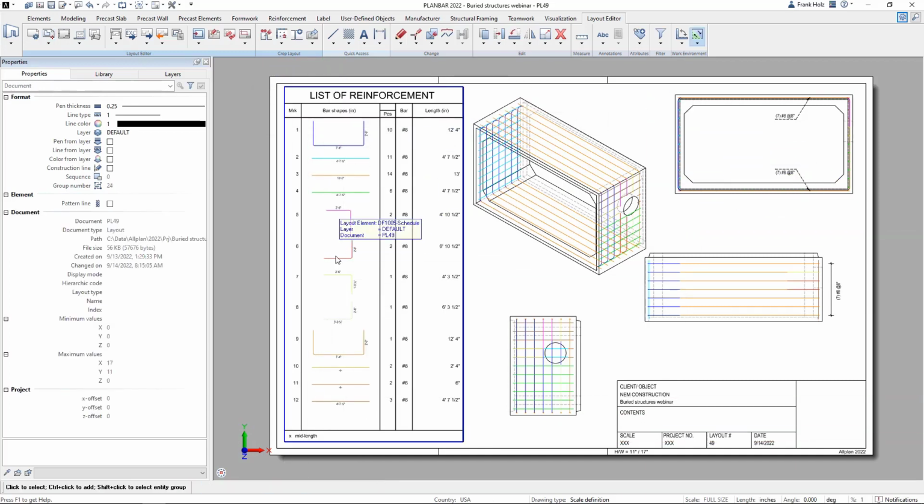And so you can see that just like in AutoCAD, it's just our 2D renderings put on our paper space here. Our title block, these are actually automated, so they're pulling information not only from the model but from the project. We also have layout attributes as well, who checked it, who drew it. You check 30 drawings that day, you can press one button, put your name on all of them. It also is good for plotting and publishing. I can say I want to see all the things that have been drawn but not checked. Or maybe if I'm releasing, I want to see all the things that have been checked but not released so that I can print exactly the stuff I need to.